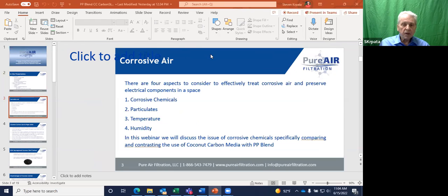There are four aspects of air that need to be treated in order to effectively treat corrosion in the air and to preserve the electrical components in the space. You have chemicals, particulates, temperature, and humidity. In this webinar, we're going to primarily deal with the issue of removing corrosive chemicals using gas phase filtration, because chemical particles are too small to effectively be used with particulate filtration. We will specifically compare and contrast the use of coconut carbon media with the use of PureAir's PP blend media.